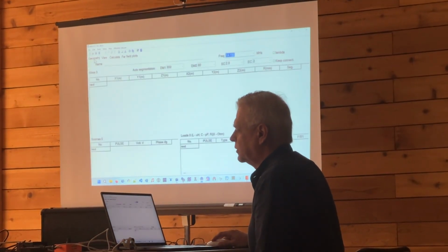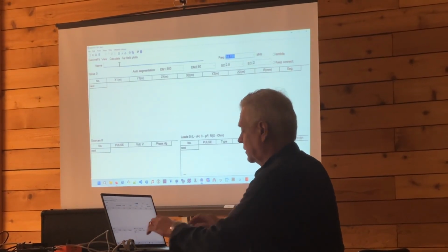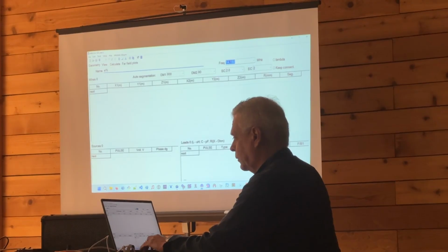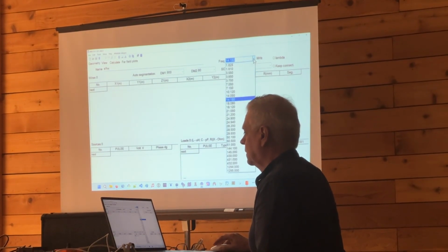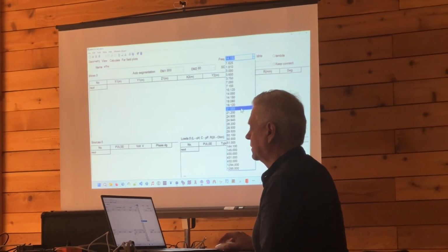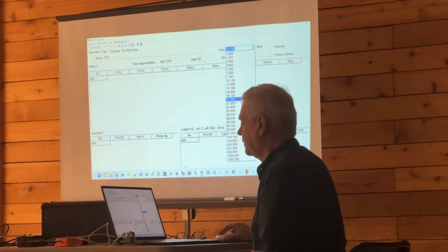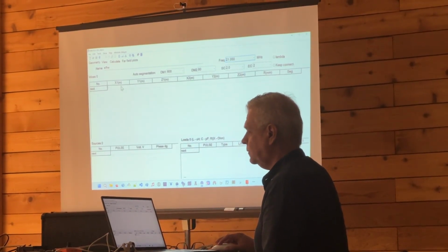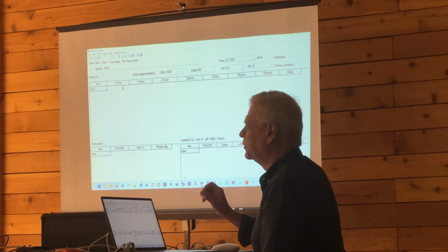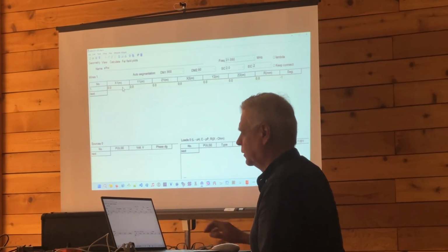So we go to the geometry tab. And here what we're going to do is title this one "end-fed half-wave." And this time we're going to try something a bit close to the edge. We've done 20-meter modeling, so let's try the 15-meter CW portion. So we'll do it for 21.050 megahertz. We do that.